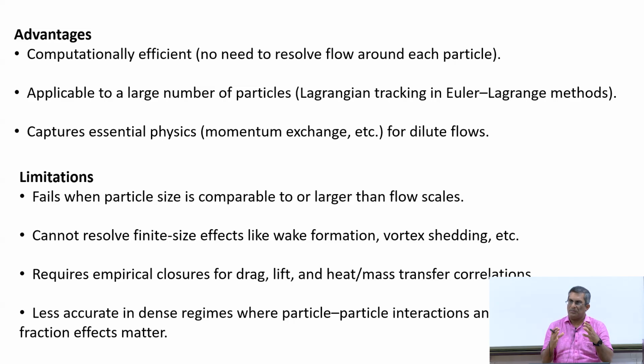What does that mean? If you see the conservation equations that we have seen, it is Eulerian for the fluid phase or the carrier phase, but it is Lagrangian for the particle phase. Then, in spite of its limitations, it captures the essential physics, for example, momentum exchange and heat transfer for dilute flow. So, this is basically the bottom line.